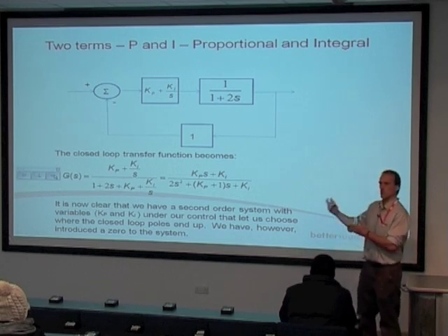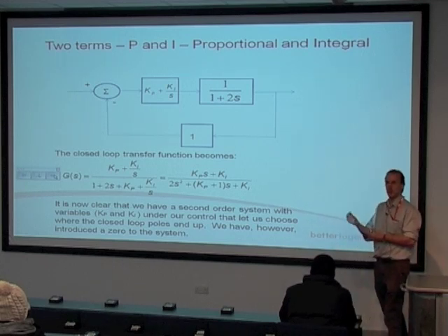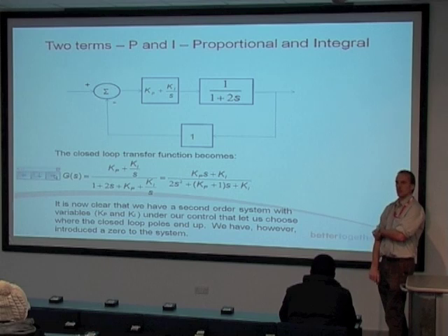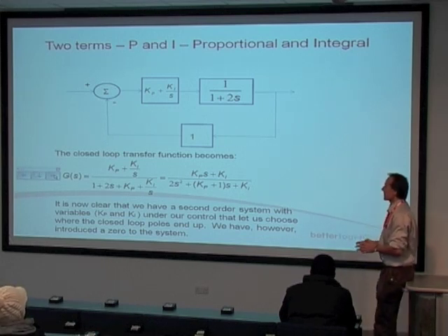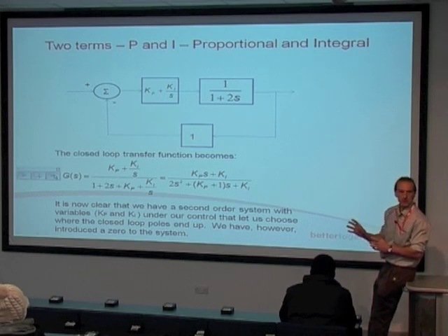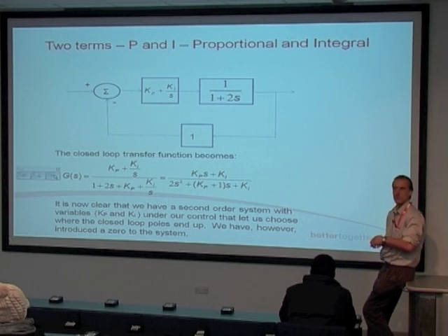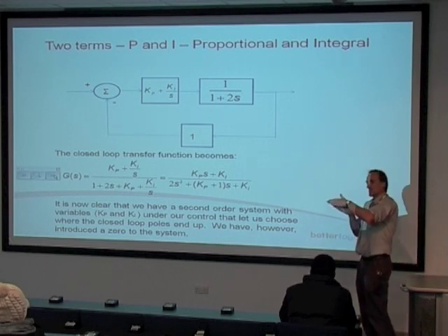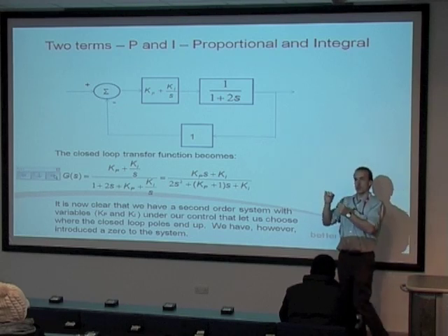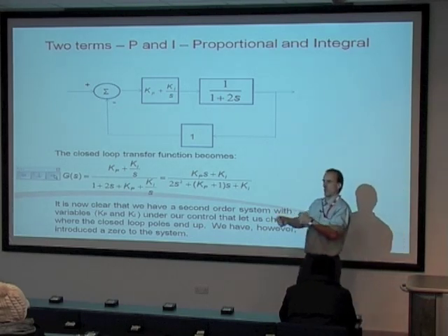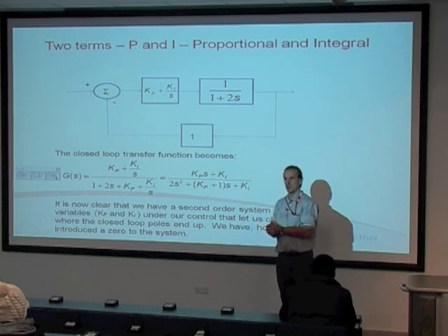Let's revert back to the example and ask yourself, well, what's the point of an integral control? And one way to think about an integral control term, if you imagine that you've got a system that's trying to control to 70 miles an hour, but it kind of gets stuck at 69, and that error of 1 mile an hour too slow really isn't enough to force the throttle open far enough.